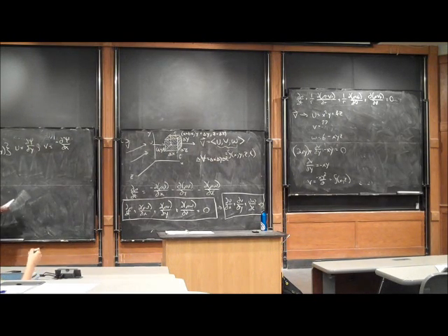Interestingly enough, psi is some function of x, y. If I set psi to a constant, that equation is a streamline for this flow field. So if I figure out what psi is as some function of x and y, and I set that equal to some constant, that equation will be a streamline for the flow field. And any constant you pick will be a different streamline. So we'll go ahead and work an example of that one too.